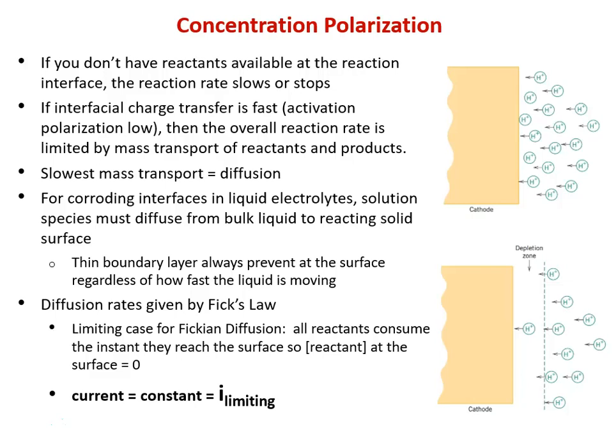Okay, well, to get that hydrogen in there to react, we had to get it from solution up to the reaction interface. And as we saw when we were carburizing, it takes time to diffuse things. Liquids are a lot faster, but it still takes time to corrode. And quite often charge transfer reactions can be fast if we have catalysts or if we drive them hard. And so in as many cases as not, we end up limiting the rate of reaction by just simply waiting for species to migrate from solution to the metal interfaces.